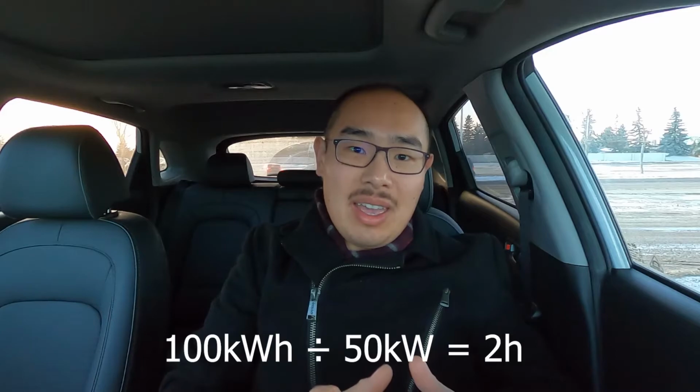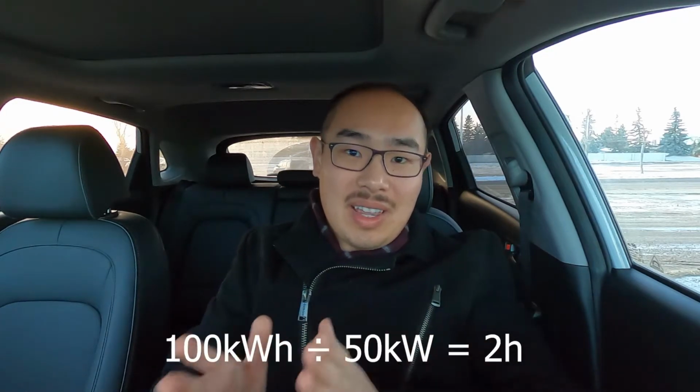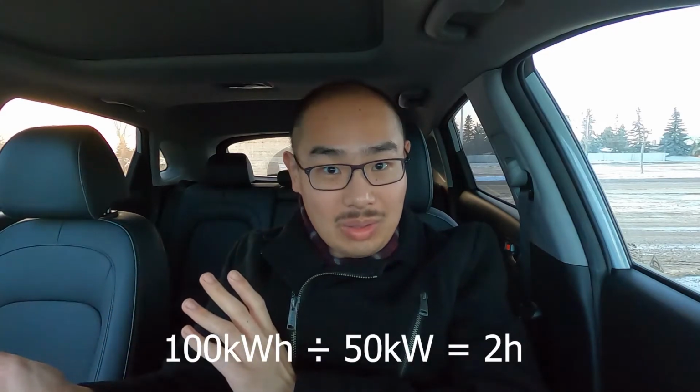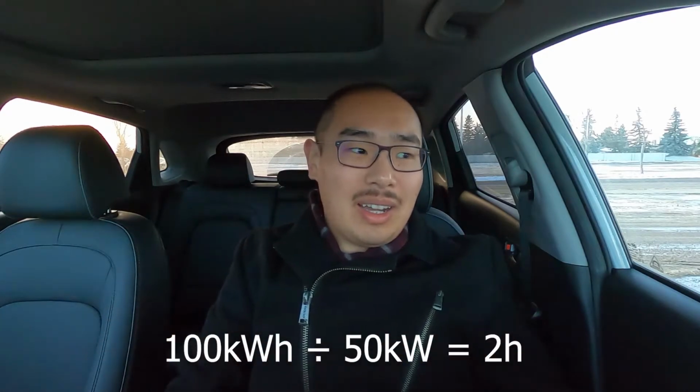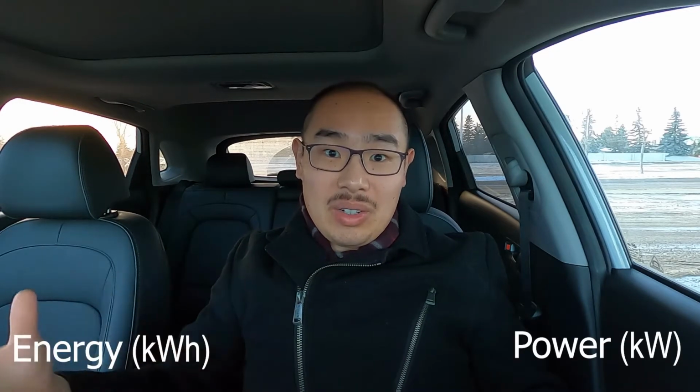If you take 100 kilowatt hours of energy and you supply 50 kilowatts of power, you can sustain 50 kilowatts for 2 hours. So you see how that works. The concept of energy measured in kilowatt hour is just a sustained power source over an hour's worth of time. So that's how you can understand the difference between the measurement of power, which is kilowatts, and the measurement of energy, which is kilowatt hour.